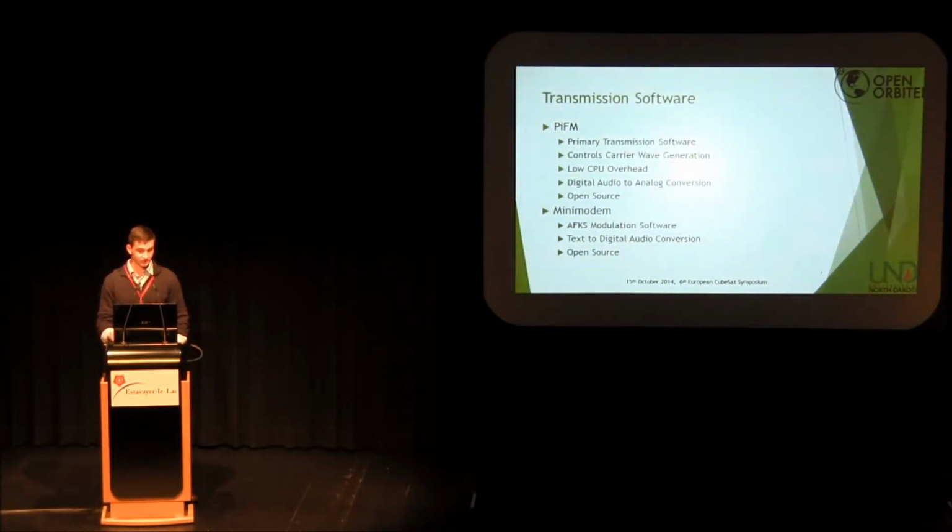So moving on to the transmission software, we are currently using two different software types. We are using software called PiFM, which is the primary transmission software. It was originally designed to play music wave files, but we were testing it to see if it could transmit actual data. It controls the output clock on the GPIO pin by dividing the main processor clock by a certain fraction to get the desired carrier frequency. And it modulates it over the wave file, or a dot wave file, for the transmission.